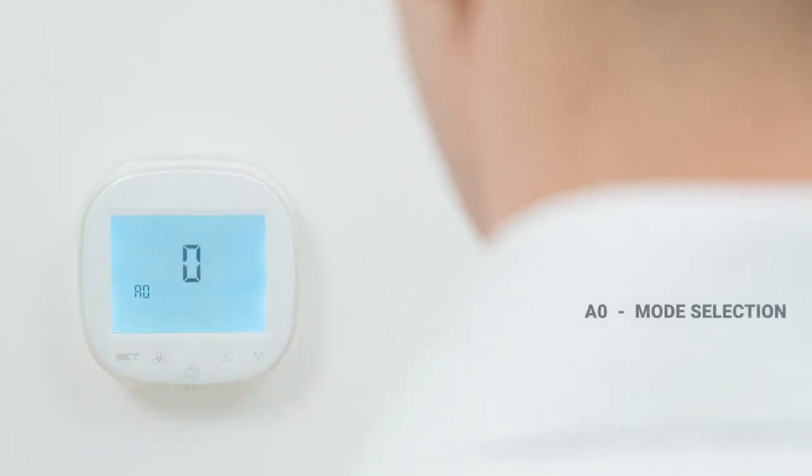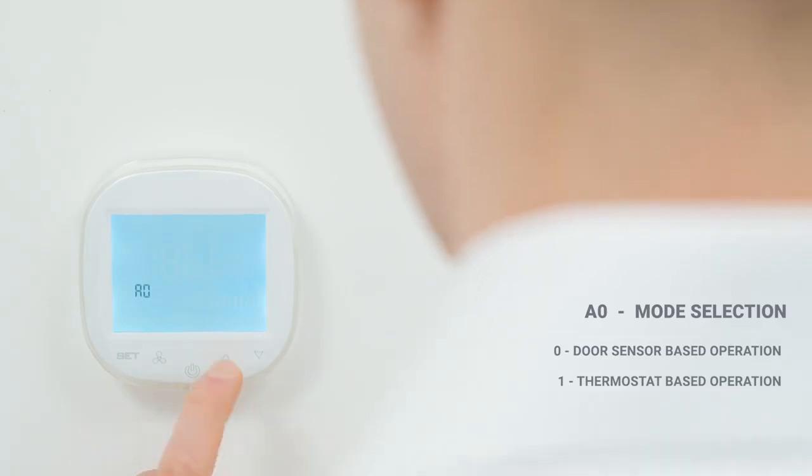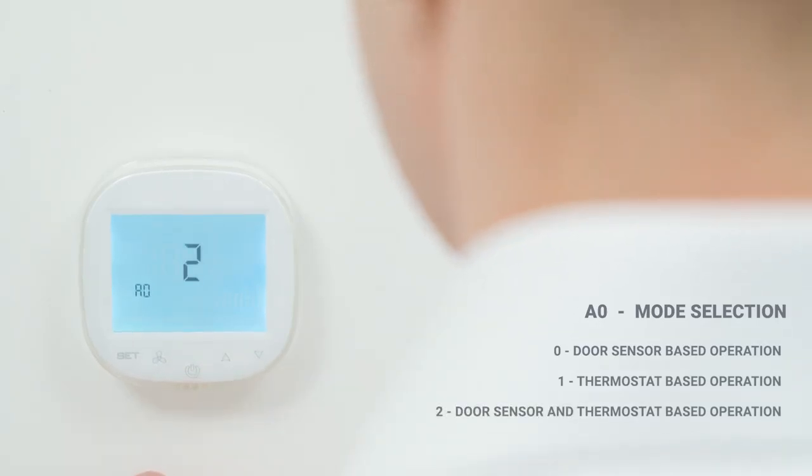Function A0: selection of operation mode. Value 0 means operation based on a door sensor. Value 1 means operation based on a thermostat. Value 2 means operation based on a door sensor and thermostat.